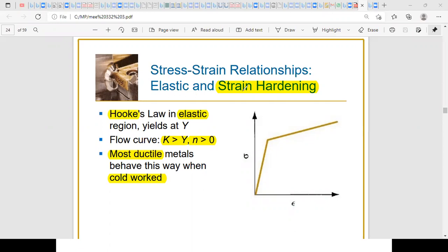Okay, look, Mahdi, it's true that the axes are called sigma and epsilon, but in reality, they put sigma, but when they present it, for the logarithmic scale you already have the paper of logarithmic scale, designed in a way that the value presented represents the log of the value, not itself. Sometimes they put just sigma, but they plot it on logarithmic scale. So when you read a value here, let's say when they put, for example, a 1, if you measure this it corresponds to log 1. When you put, let's say, K, and you measure this, you get log K.